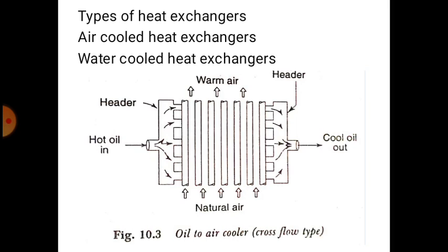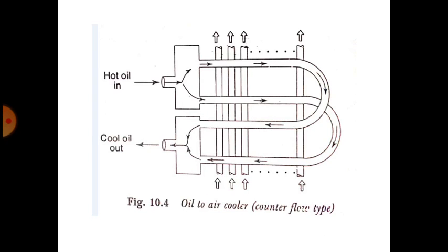This is one type of heat exchanger. You can use parallel flow, counter flow or cross flow type heat exchangers. This is another type, the counter flow type. You can see the hot oil in and cool oil out, and there is an air flow in the counter direction.